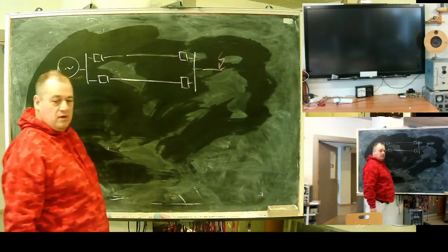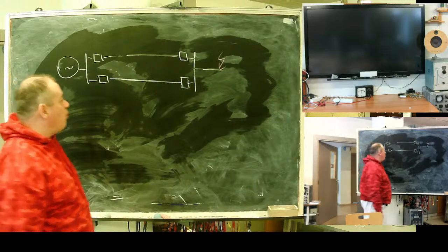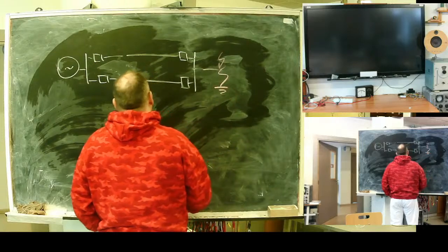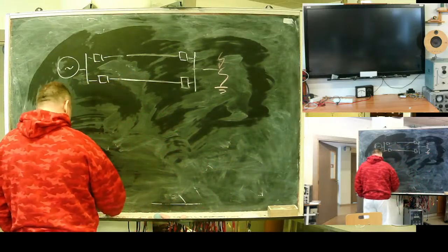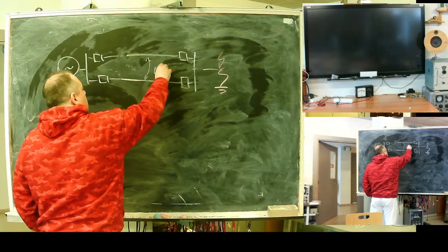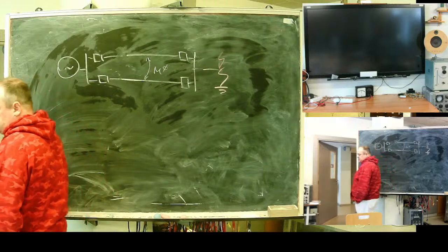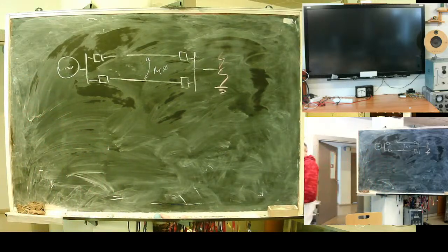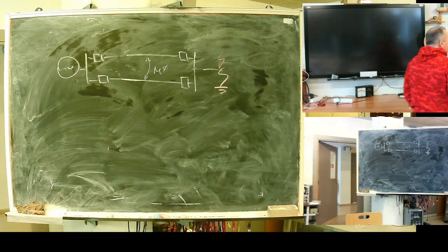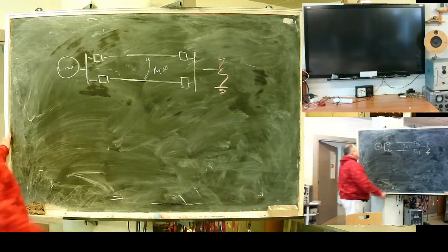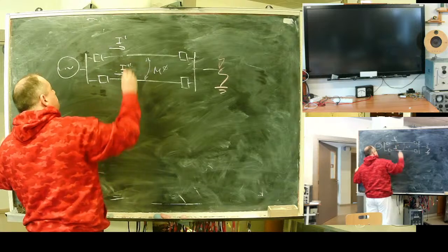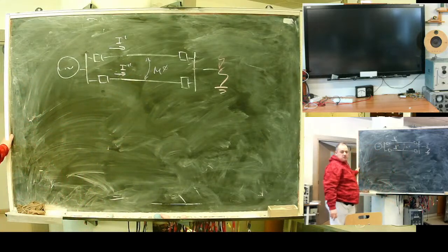This problem persists only in case of earth faults to the ground. Your parallel lines are coupled with mutual inductance. Real significance is only in zero sequence. Here, I1, I2. Only significance is in zero sequence.